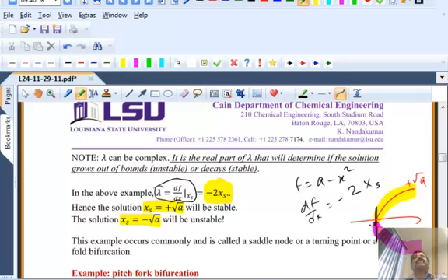And this whole area of bifurcation theory is about locating such critical points. In fact, if we want to find out the critical value of Reynolds number where the stability changes, we will look for that particular condition, that one eigenvalue must be 0. Okay, exactly one eigenvalue must be 0. Now, what happens if there are two eigenvalues that are 0? Okay, it leads to more complicated dynamical situations, which are beyond the scope of what we can do in this course. Okay, but it's a very perceptive question.